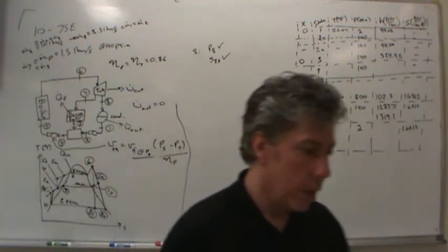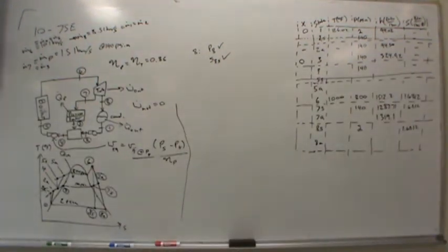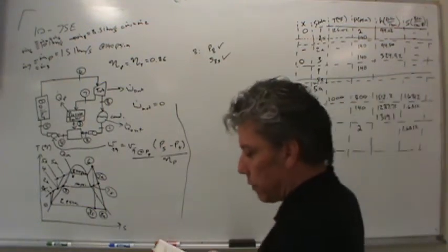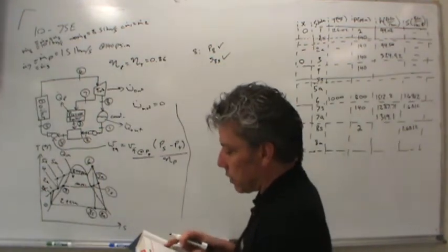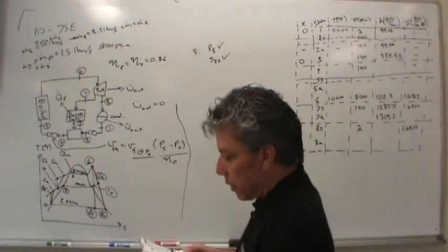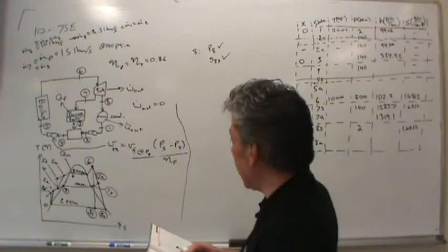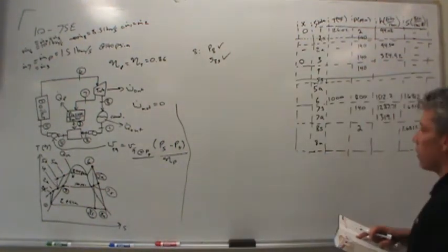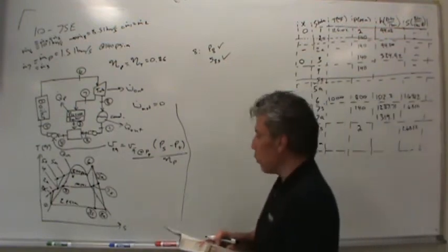Let's go to a pressure of 2 psia in the saturated tables. I just passed it. So page 966 again. At a pressure of 2 psia, the entropy of saturated vapor is 1.9194. The entropy we have for state 8S is 1.6812, significantly less than 1.9194.